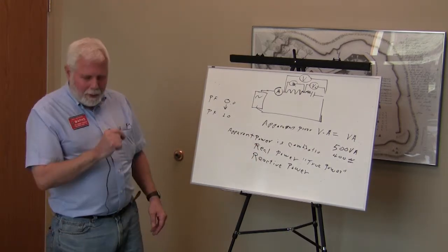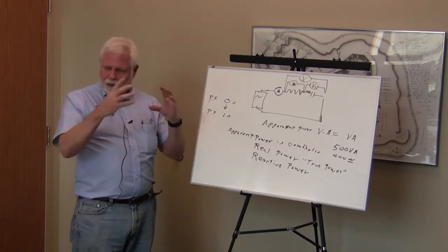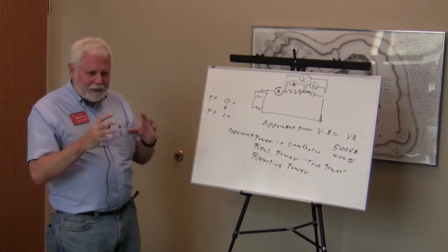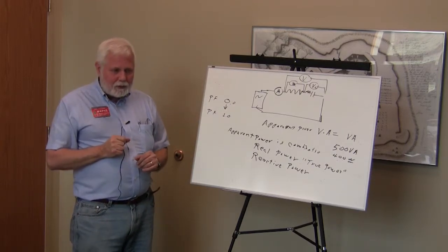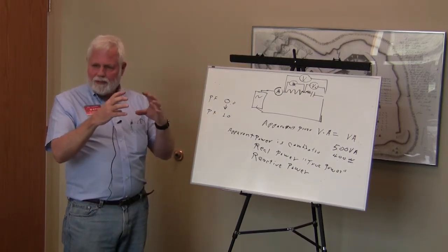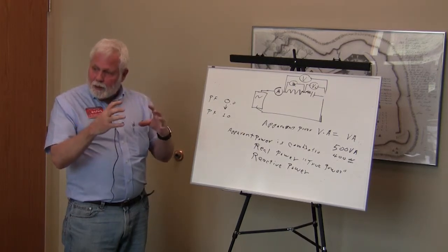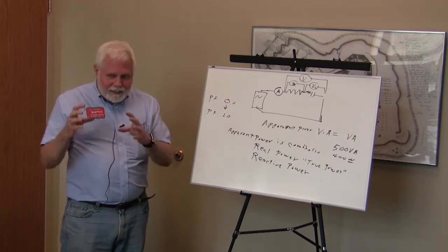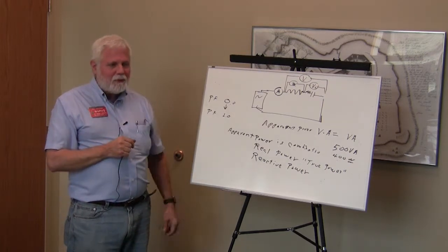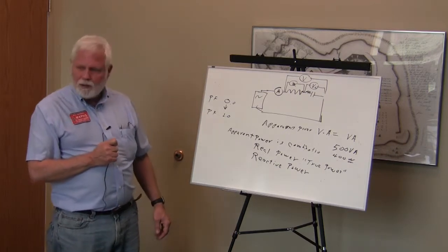Good news, folks. You know that power meter outside, with the dial spinning and so forth? That is measuring true power. It's not measuring apparent power. That's why it's somewhat more complicated than just a voltmeter and an ammeter, because it's actually measuring true power. The nice thing is the good old electric company is only charging you for true power. They're not charging you for apparent power. Only true power on your electric bill.